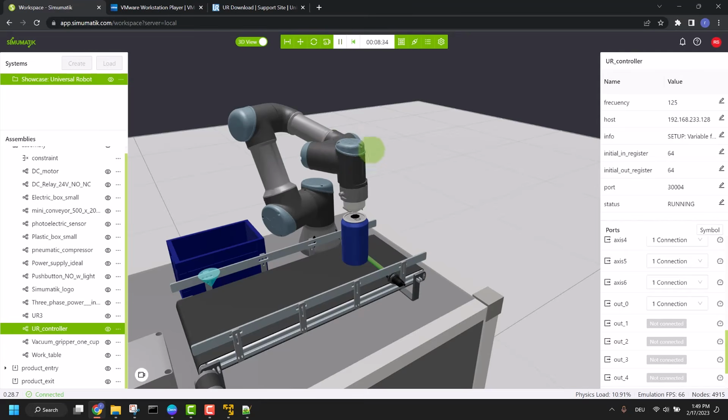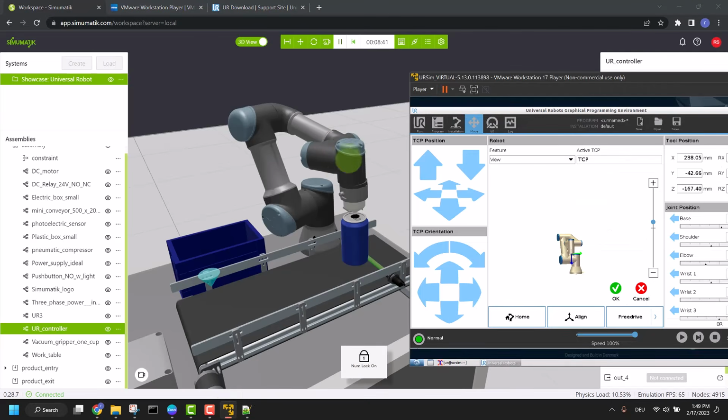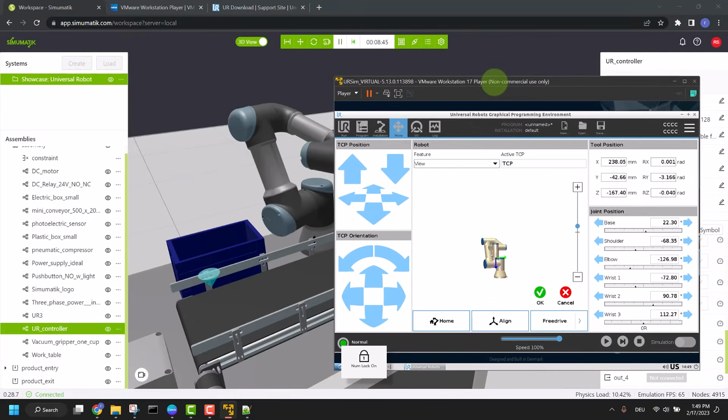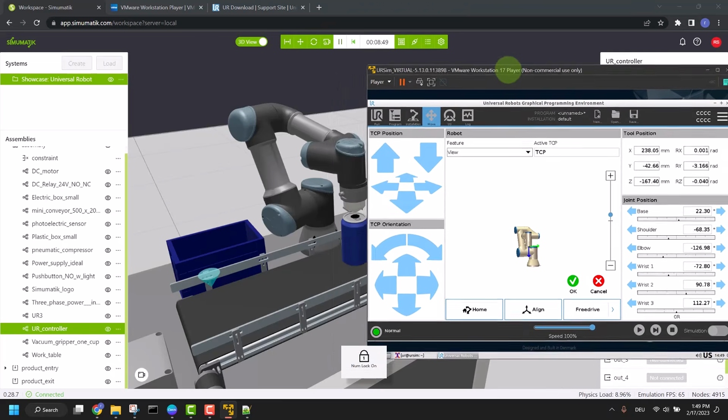So we wanted actually a home position, but if we moved here, this is just a small way to find your home position more easily. So first you go to pick position, and this is, like I said, every programmer has a way to program the robot. So I prefer to first go to pick position, and I go to my program. So when you go to your pick position, click OK.